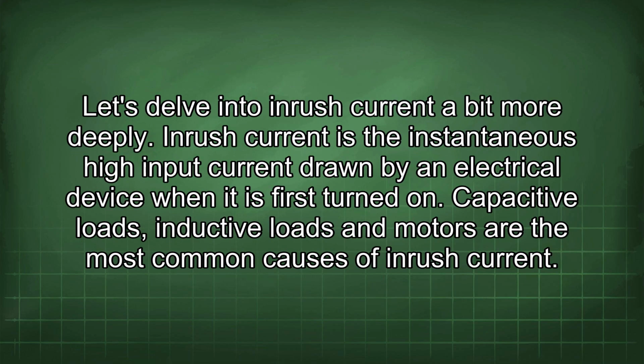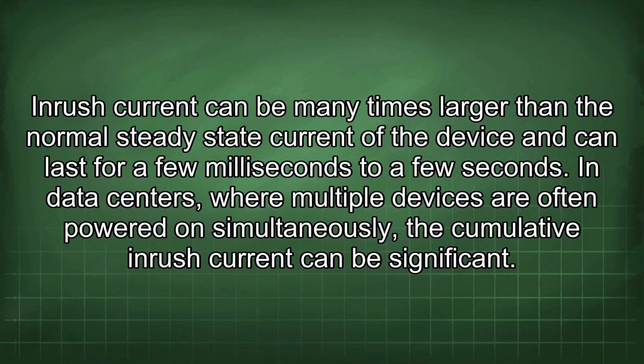Let's delve into inrush current a bit more deeply. Inrush current is the instantaneous high input current drawn by an electrical device when it is first turned on. Capacitive loads, inductive loads, and motors are the most common causes of inrush current. Inrush current can be many times larger than the normal steady-state current of the device and can last for a few milliseconds to a few seconds.